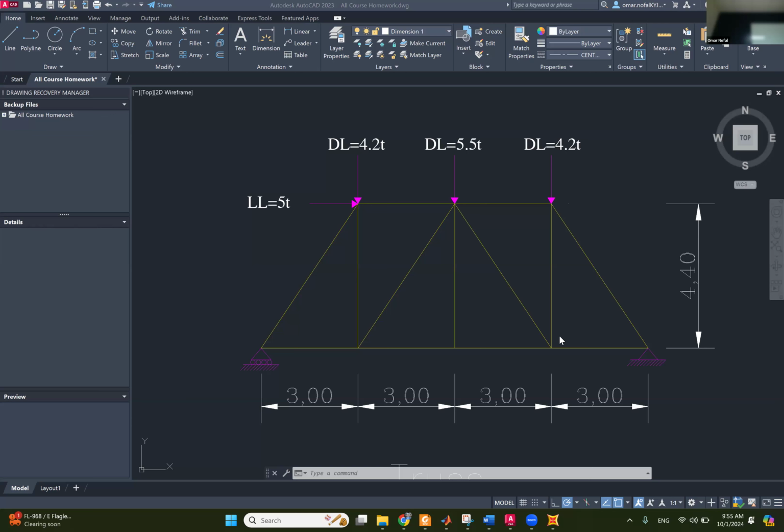Because if you consider the own weight in the structure analysis of trusses, all the trusses that you have solved are going to be like beams. They are going to have a bending. So you have to draw bending on the truss, but we know that the trusses don't take bending moment, right? Because the own weight of the truss structure is small with respect to this weight.